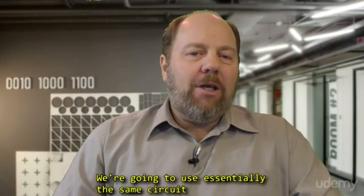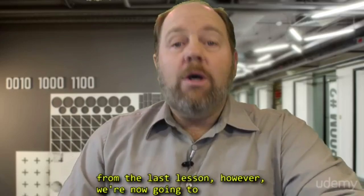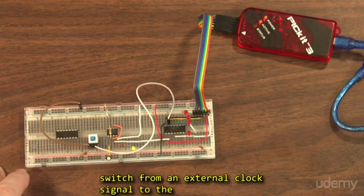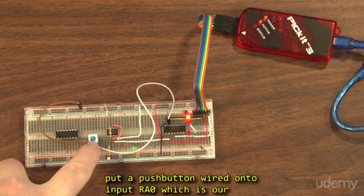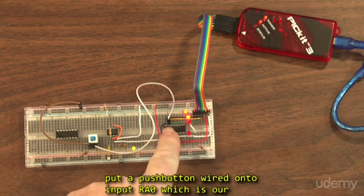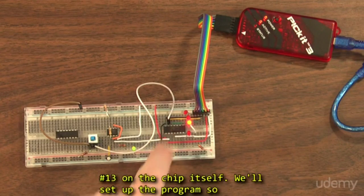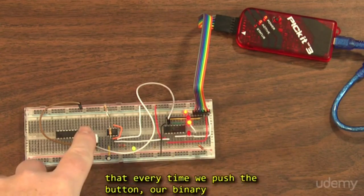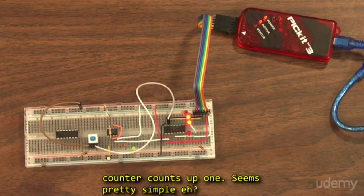We're going to essentially use the same circuit from the last lesson. However, we're now going to switch from an external clock signal to the internal clock running at 16 megahertz. We're going to put a push button wired onto input RA0, which is our digital input-output on port A. This is pin 13 on the chip itself. We'll set up the program so that every time we push the button, our binary counter counts up 1.